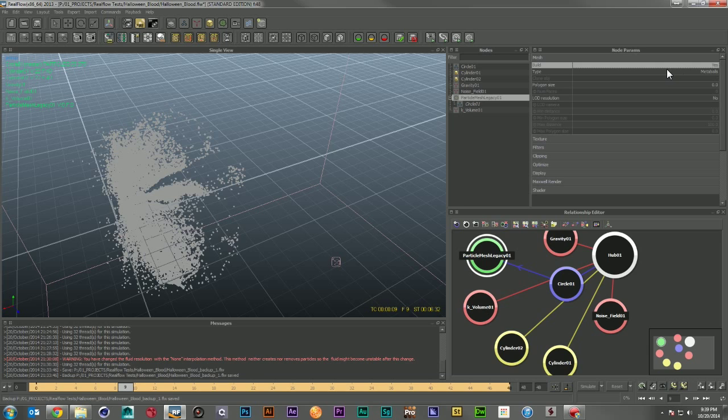So if I come into my mesh options, the first thing it's asking is, do I want to build it? Yes or no. What am I looking for? Am I looking for metaballs and polygons, clone objects? I want to stick with metaballs. And then the polygon size is something that you're going to kind of have to feel out. I'm going to start off with 0.1, which I know is going to be way too big. But I also want the first couple times I try to test this for it to move very fast and then kind of hone in on it.